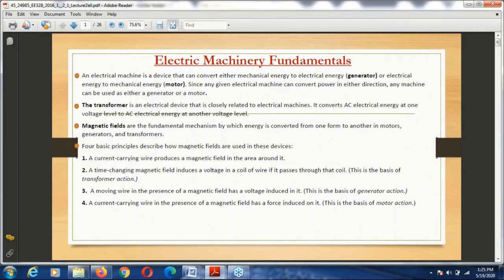Now, Faraday's law states that if a flux passes through a turn of a coil of wire, I've explained what is meant by coil of wire. I've also used thread to illustrate it. Faraday's law states that if a flux passes through a turn of a coil of wire, a voltage will be induced in the turn of wire that is directly proportional to the rate of change in the flux with respect to time. Is it clear to you? Now you have the illustration there, e induced equals N dΦ over dt. Is it clear to you?